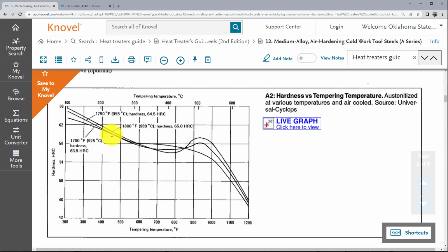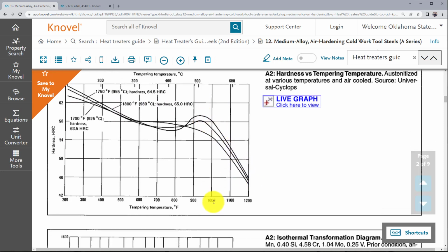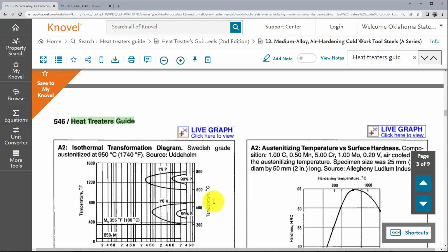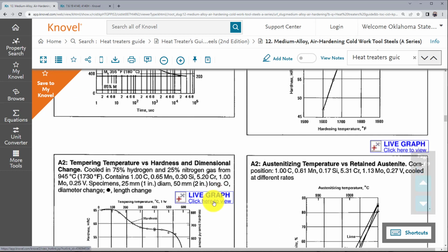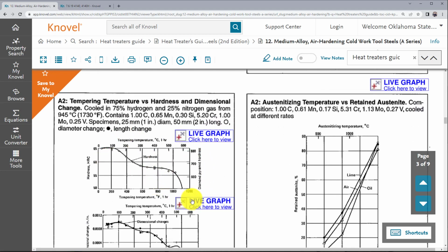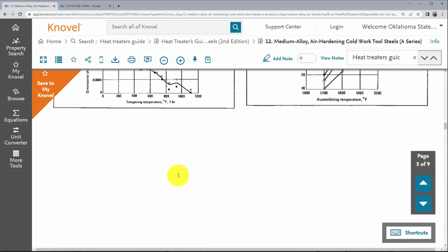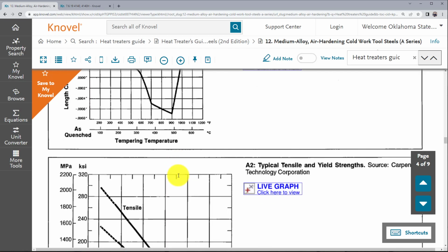Now there's other tool steels like an H series, and that's a hot working steel, so hot forging die steel materials, that would even hold its properties even better at these temperatures. So it's not going to temper as much until we get down here to this further temperature. And so that's going to give you some ideas. And again, you could go through this, and this has tempering and dimensional changes that might come with this. We see a lot of the A2 tool steel making precision parts, heat treating in a protective atmosphere and holding tight tolerances and not seeing distortion or change in the part.